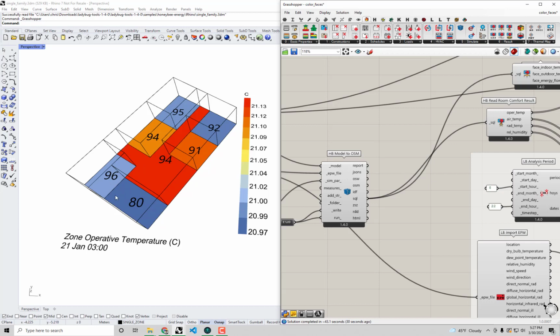So we remember, right, this room was all the way down in the 50s or 60s before, right? Now it's all the way up at 80%, which is still not perfect for sure, but this is a big, significant improvement. There's definitely a quality and value that has been added to this building by using these better performing constructions, both the better performing windows, and I'm sure that those thermally massive walls, tighter envelope with less leaky air also helped quite a lot too.